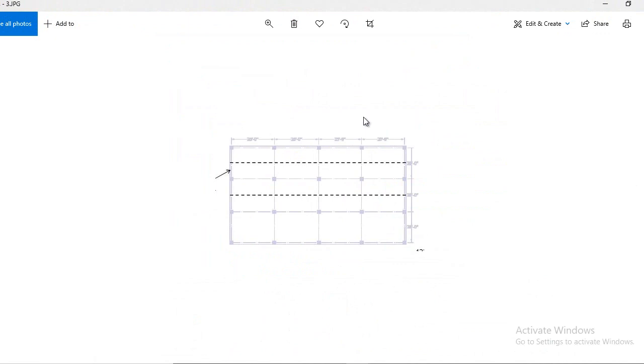We did this example, and in it this span is 25 feet and this is 20 feet. All the spans in the x direction, the east-west direction, are 25 feet, so the adjacent spans are equal. In this case there is a little unbalanced moment. Remember, the unbalanced moment should be caused by the live load, not by the dead load.